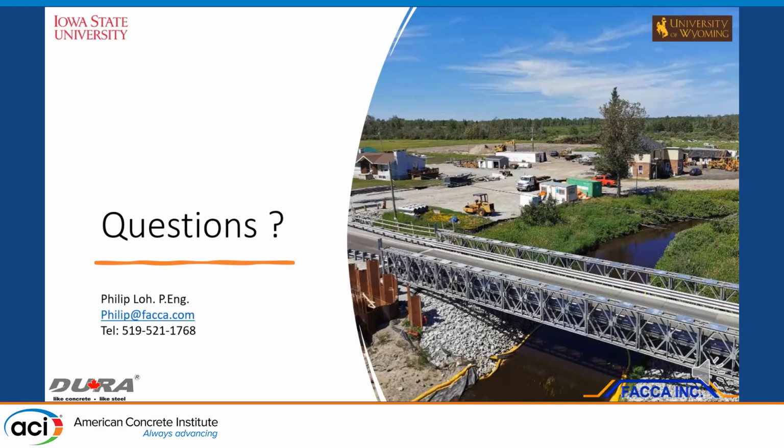My answer is that if you look at the per meter length of a pile, obviously UHPC is going to be more attractive. In this case, it's a first project, and we wanted to try it out. Even as a change proposal, when you build a project, the piles are always paid by per foot or per meter. I don't know how you guys do it, but in fact, we did not get paid as much, because it's only 9 meters instead of 13 meters. So that's the thing. Okay.